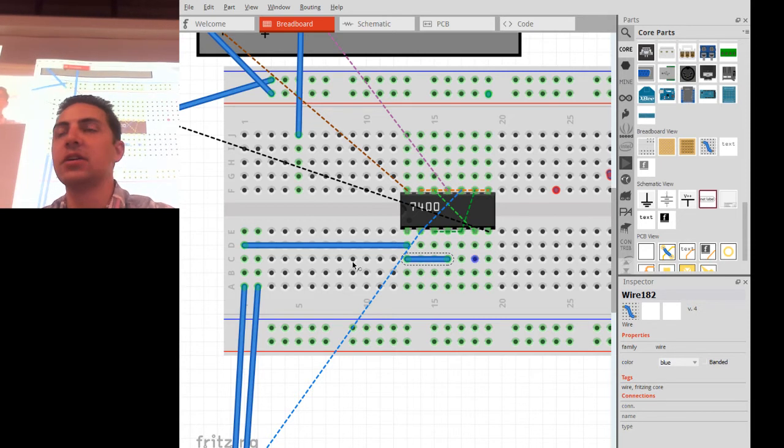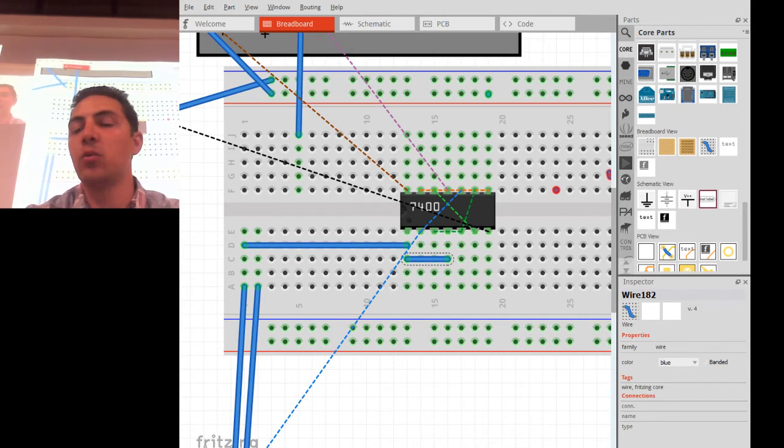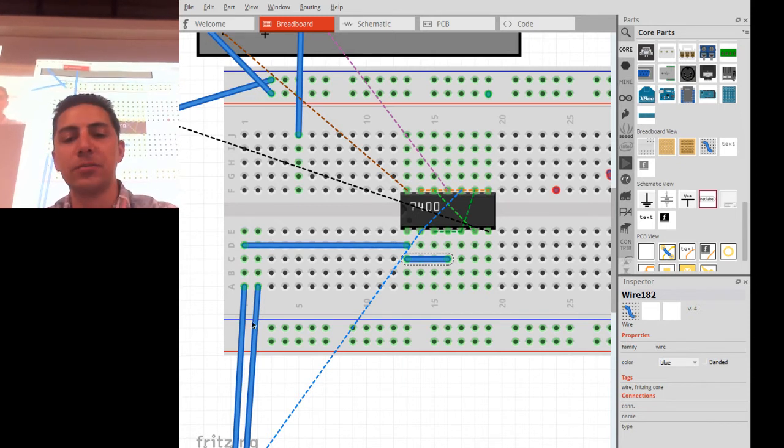All right, now at this point, I'm getting a few wires on this board. It's becoming difficult for me to know which wire is which signal, which is where the next part of previs comes in. We want to be able to clearly delineate at a glance what signals go where. So I'm going to make use of the fact that we can colorize these wires.